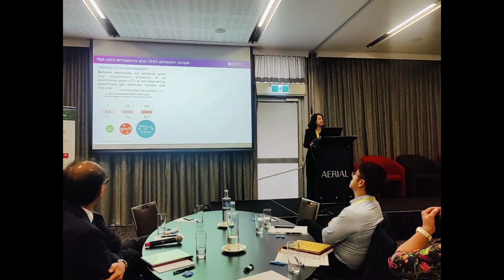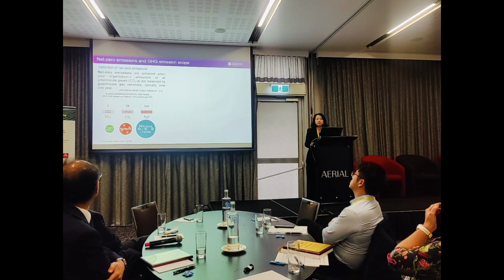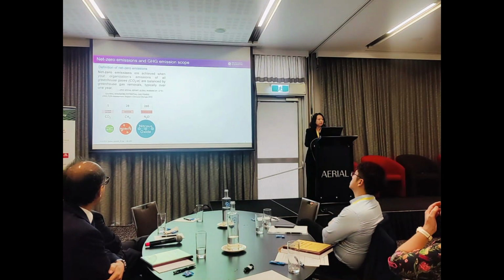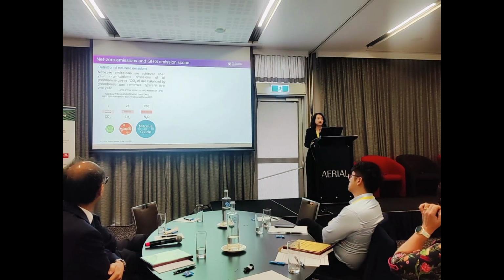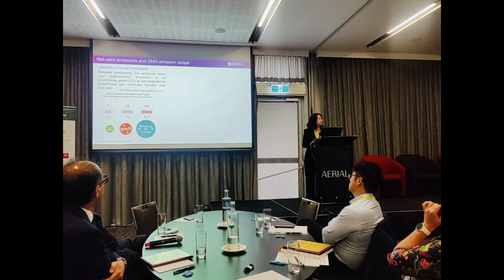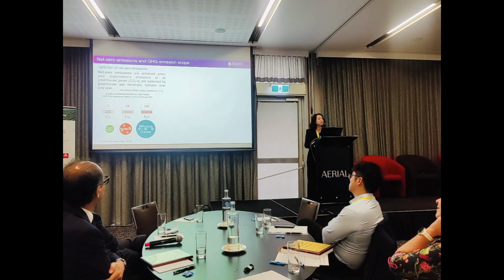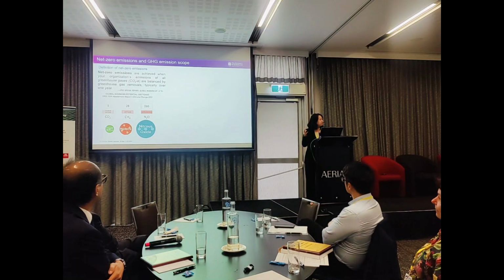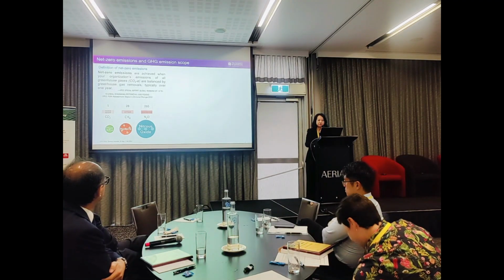The definition is that when we look at greenhouse gas emissions, we don't just look at carbon. We all know it's CO2 equivalent. We convert all the greenhouse gases based on their global warming potential. If we treat CO2 as one, then methane is multiplied by 28. The other one, which is very common from wastewater, is nitrous oxide, generated as part of the nitrogen removal process. We have to multiply it by 265, or the newest number maybe 273, into CO2 equivalent. To get net zero, we have to make sure all these add up, and the CO2 equivalent is offset or balanced by the carbon being removed by the organization.